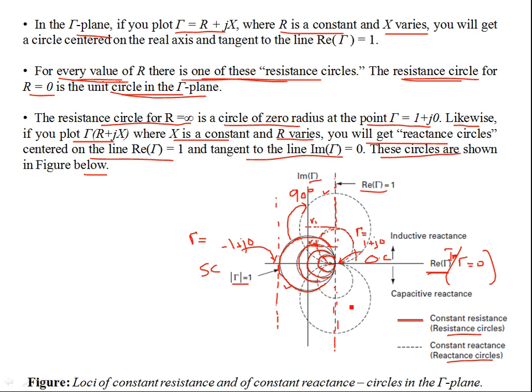But usually in the Smith chart, you trim the circles outside gamma equal to 1, since you don't have anything outside it. You consider the circles inside gamma equal to 1 for passive resistances, or for loads whose resistance has a non-zero real part. If you want to locate, for example, a load ZL which has a real part RL, equal to RL plus jXL, then you use a chart like this.